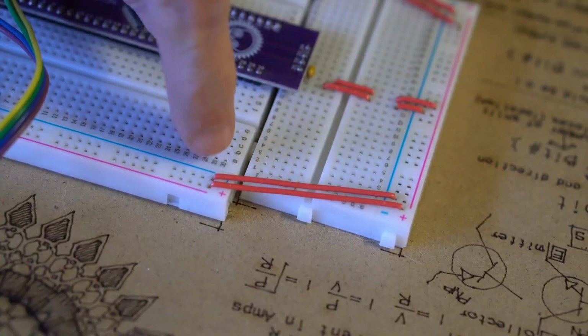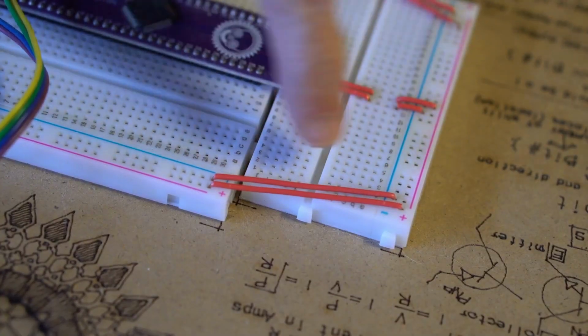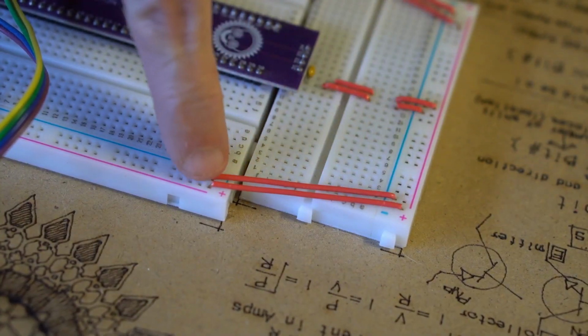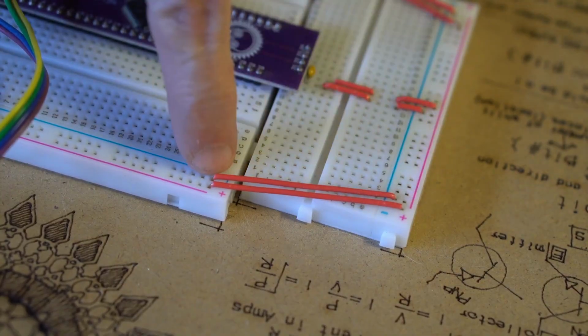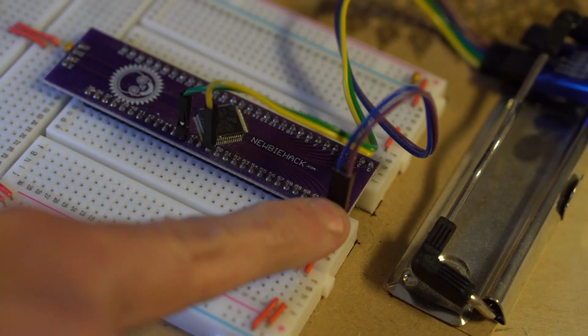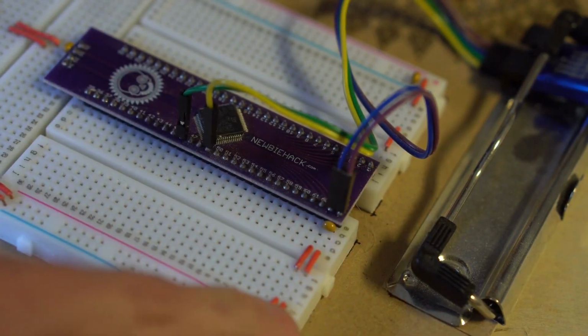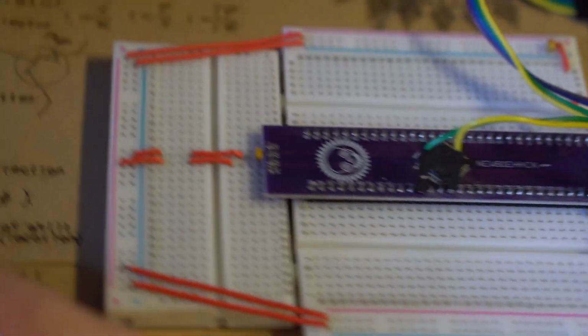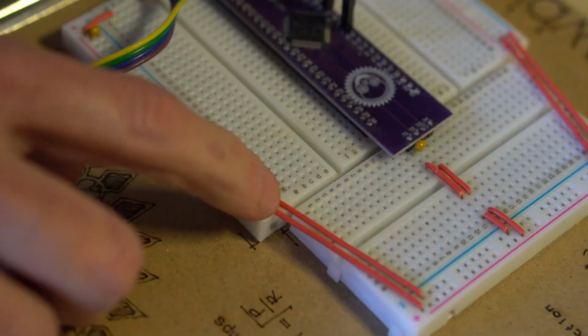And these two breadboards need to be connected for power as well, so positive goes to positive and negative goes to negative. So when 3.3 volts and ground is connected to these two pins, it will power the rails along the entire length of the power rails on all of the breadboards.